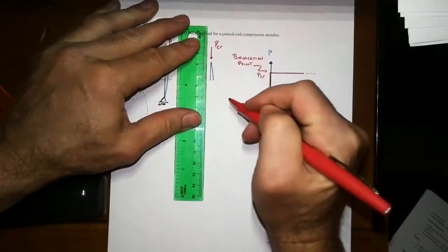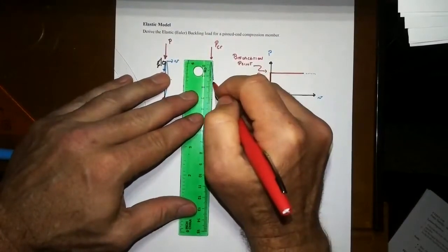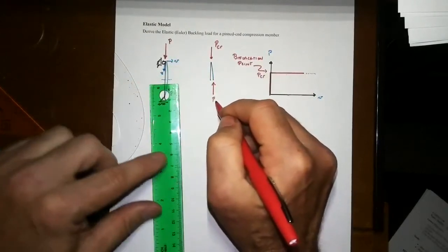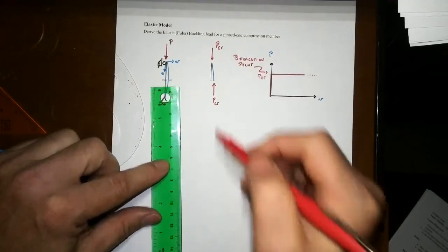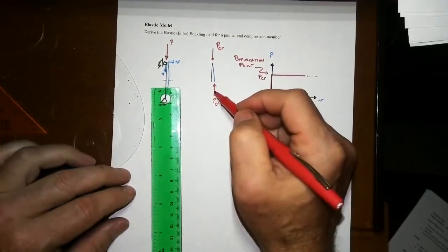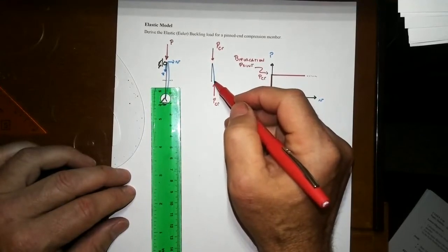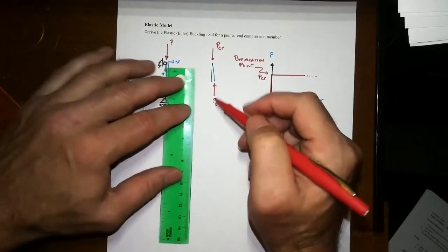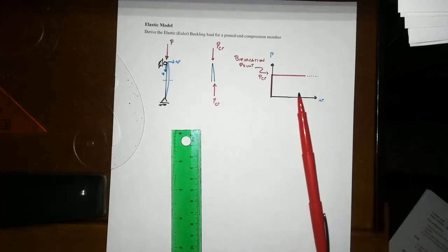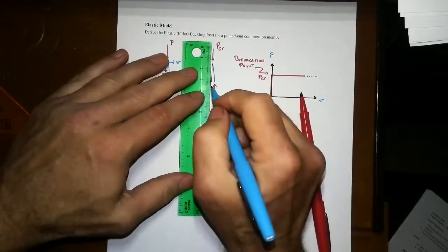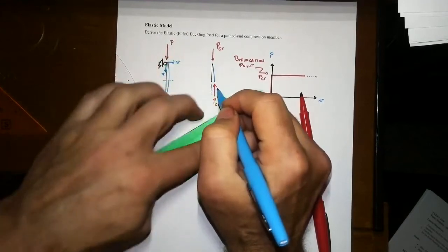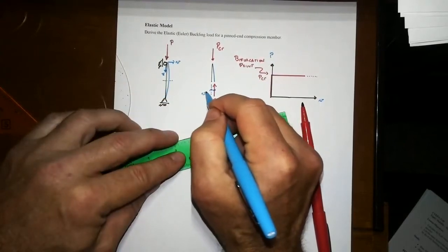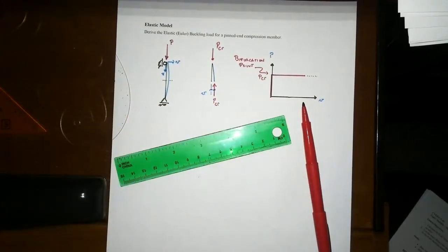When it happens, that's at P critical. So we have then an axial load in the displaced position that is offset. Of course, by axial equilibrium, these two will be equal and opposite. This is purely vertical because the centroidal axis, the longitudinal axis of the member right at this point, is going to have 0 slope. Now, it is offset though, and that's a critical thing to realize. And we're using that little symbol lowercase v here. Some texts and people that derive this will use lowercase y for that deflected position.